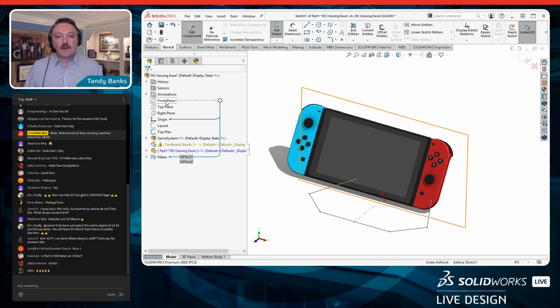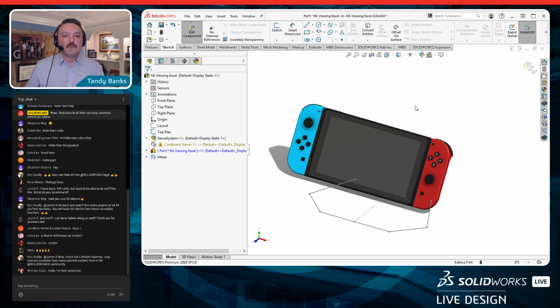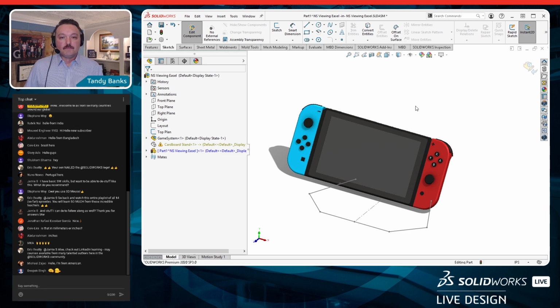Now, because I want to start with my plan view, which is on my top plane, I'm going to start extruding that up to begin with today. I'm just going to simply use the confirmation corner, and I'll accept the sketch in order to get out of that front sketch. Over in the feature manager area, it's now highlighted that component that I'm working on in blue. That lets me know that I'm in edit part mode. I'm not in edit assembly mode, I'm in edit part mode, and that's an important distinction to make whenever we're working with assemblies in the context of part design.